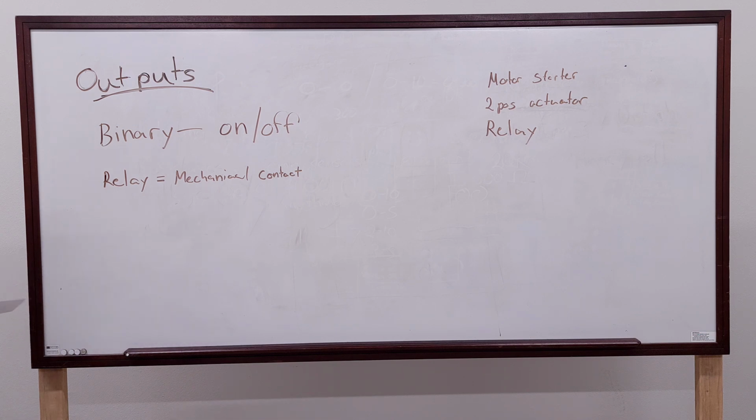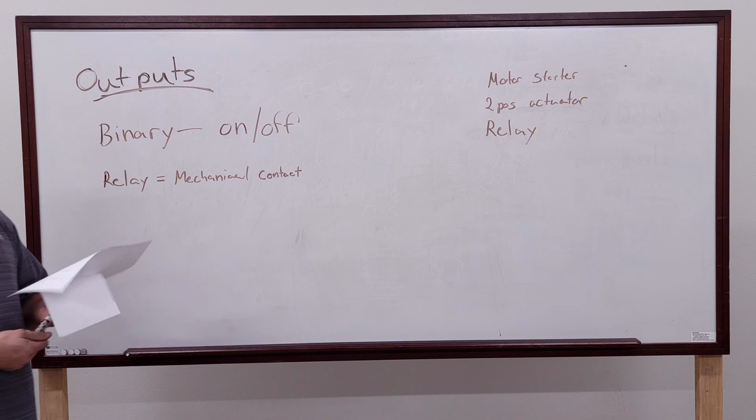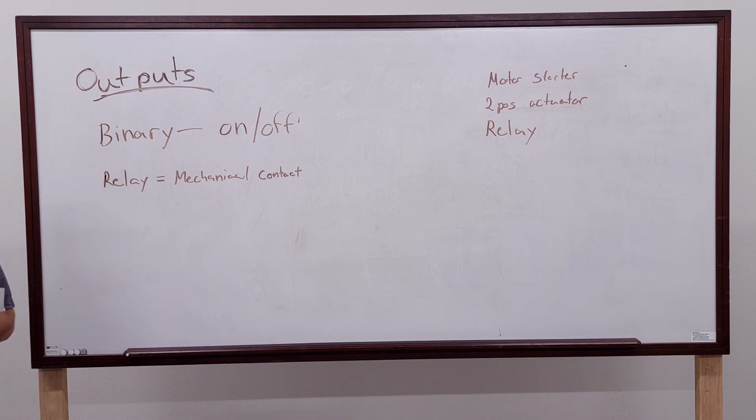So, when Honeywell first came out with their controllers, they had Triacs and they were rating them at 1.3 amps, which is great. But then people started putting them on heaters without isolation relays, and the contactors would fail, or they would start to chatter and they'd increase the amp load and would burn up all the Triacs in these controllers after like 2 or 3 years. So Honeywell put out a memo like, hey, no, we definitely, and if you read their documentation, it said to use an isolation relay.